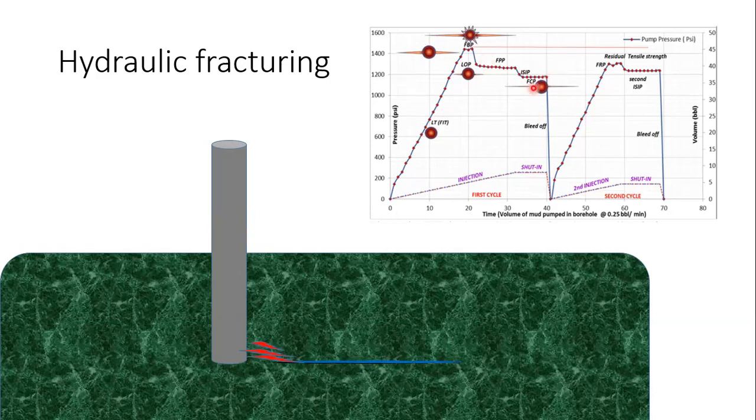So the difference between ISIP and FCP. FCP is the point before closing, like before closing the fracture. After reaching FCP, the pressure will drop abruptly and finally it will attain its own position. So the time taken from ISIP to FCP is the potential capacity of that fracture to withstand in that formation to allow fluid to flow through it.